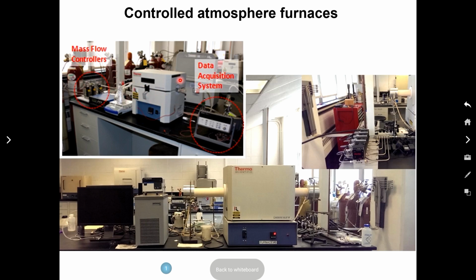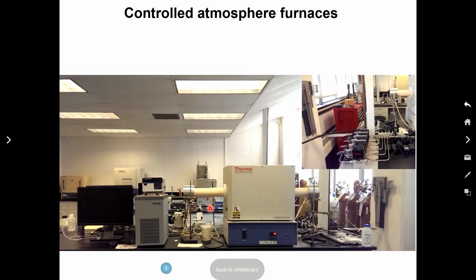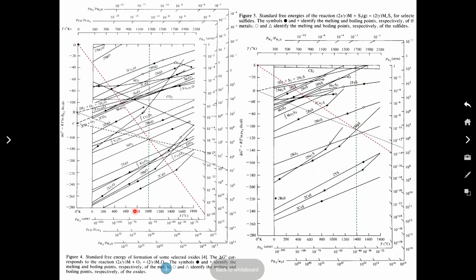So depending on the temperature, you can create this controlled atmosphere inside a quartz tube or inside a ceramic tube. Then you'll basically be turning the CO2 knob. You can turn the temperature knob as well, because CO2 and temperature will go in sync. On the Ellingham diagram, you can choose different temperatures and you will get different answers.